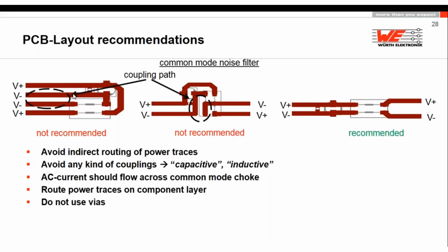So this is an experience which was given from a customer. The customer went to the EMC lab. He failed. He asked for support. We helped him somehow. We were with him in the lab, and because he failed, we found the solution. We put an in-air PCB: we soldered two capacitors directly to the connector, and we soldered an additional common mode choke. And we found out, hey, with this solution, he will pass the EMC test.